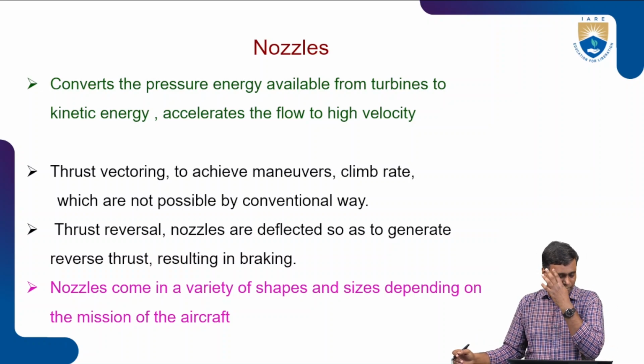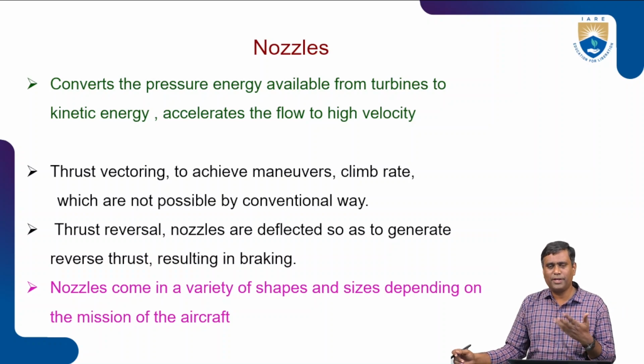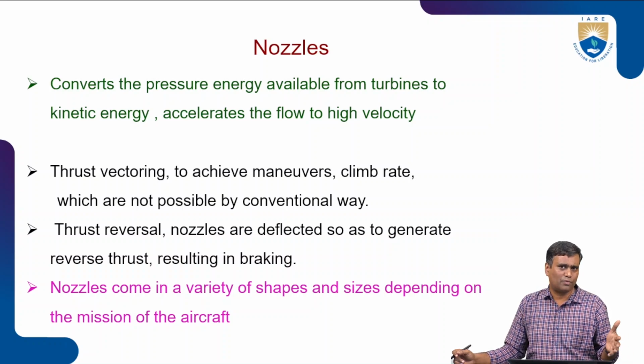Then immediately after, through the diffuser, those highly pressurized gases at high density will enter the combustor, where fuel will be mixed and the combustion process will take place. In the combustor, actually only a quarter of the air is used for combustion, and the remaining air shields the combustor so that high temperatures do not really touch the combustor walls.